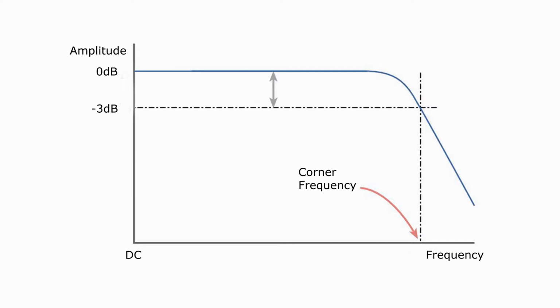The word cutoff is a bit of a misnomer because in electronic implementations of low-pass filters, it neither cuts off nor is it the actual starting point of attenuation. That's why Alligator Technologies prefers to call it the corner frequency.